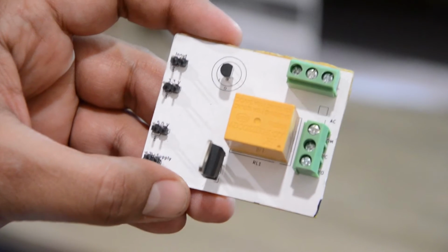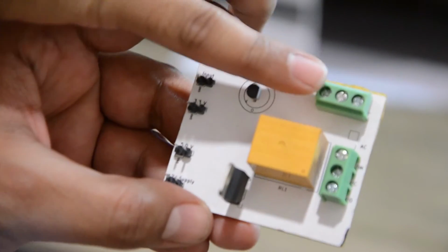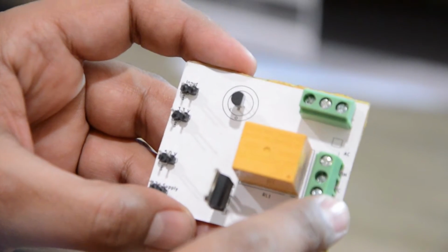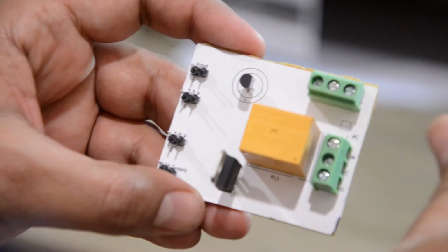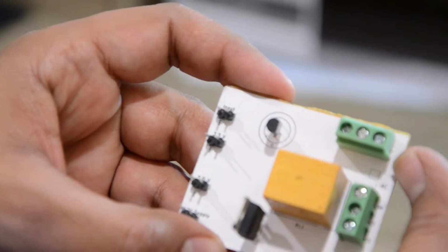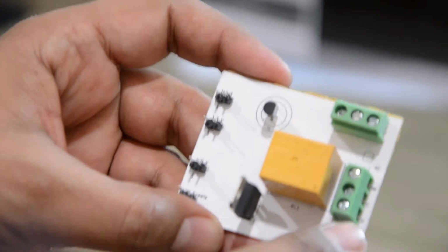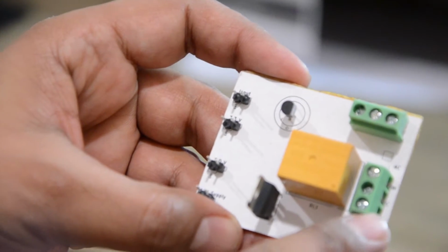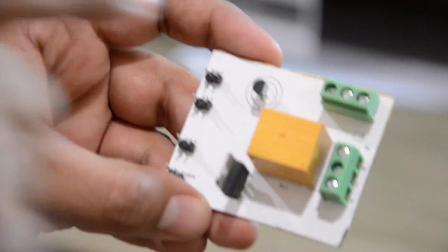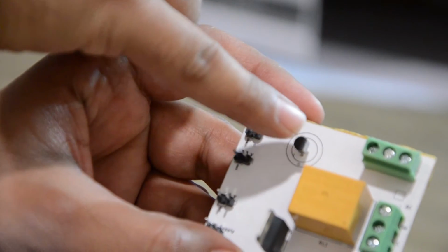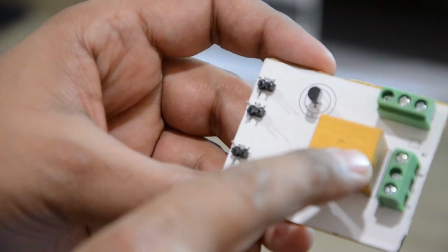So this is the close look of the relay board. We have the input over here and the output. So let's say we are controlling the LED bulb that we were looking at. This would be the 220 volts AC input to the board, which I would be connecting to the wall socket. This is the output, which means 220 volt output, which I would be connecting to the appliance. And we have a transistor, in this case BC547, and we have the relay.